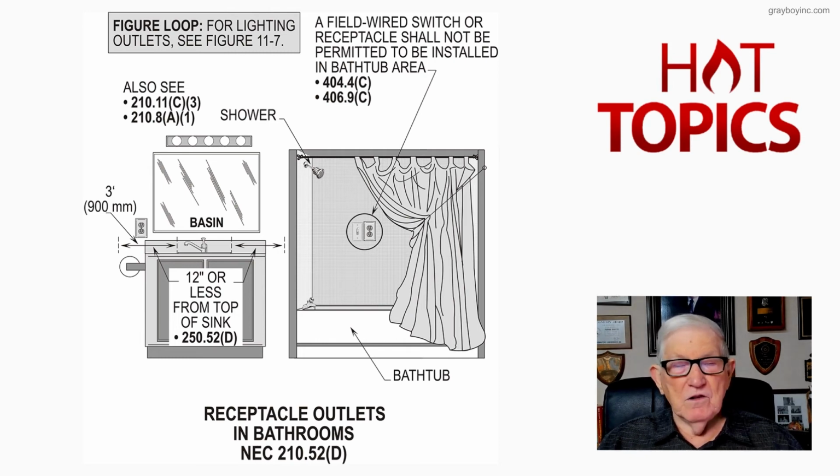210.52(D) as in dog. And we bring that 20 amp circuit into the bathroom area, and that's what this figure 10-15 is illustrating: receptacle outlets in bathrooms installed in accordance with 210.52(D) and inside a shower or inside the bathroom.